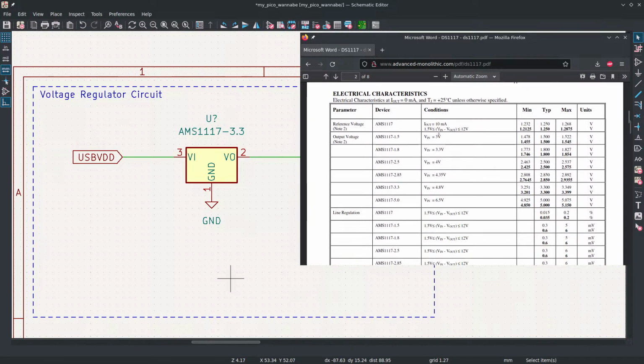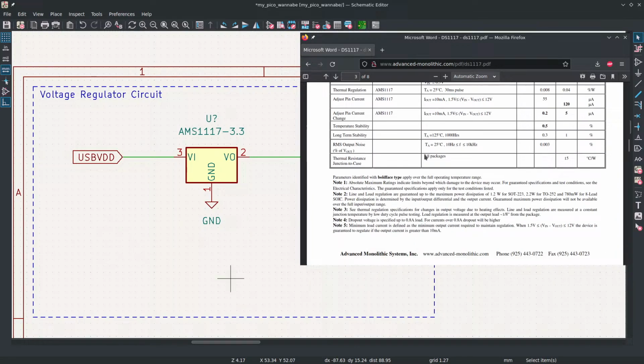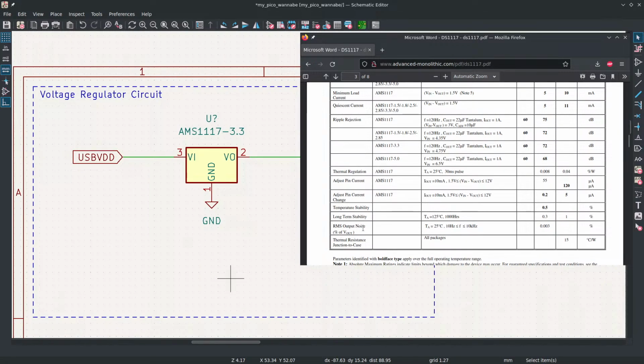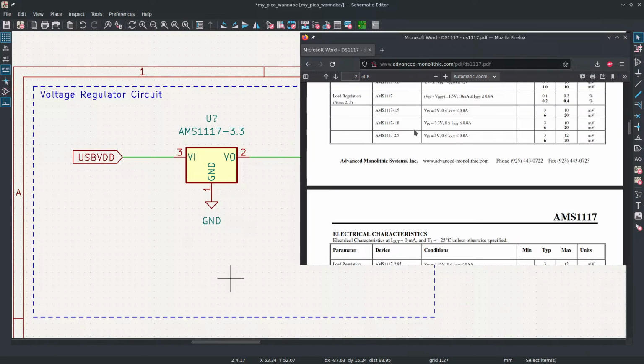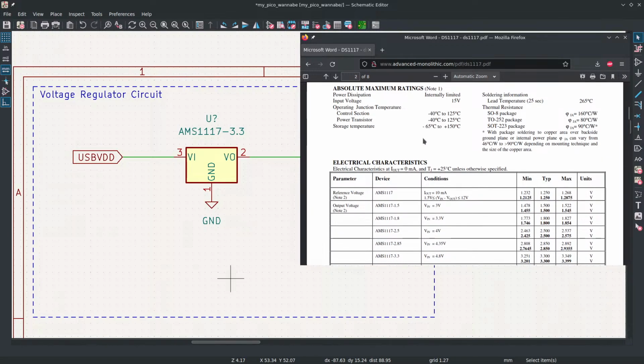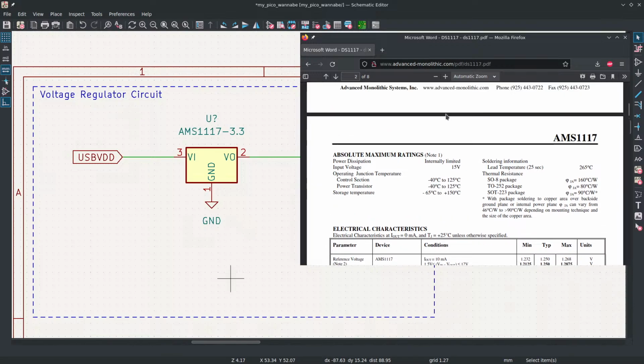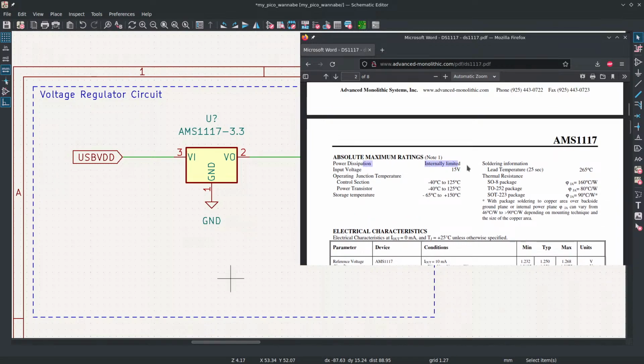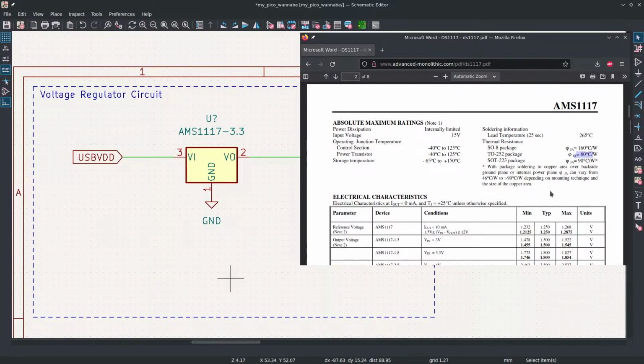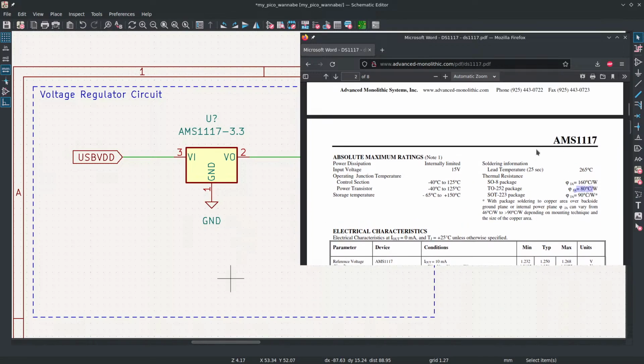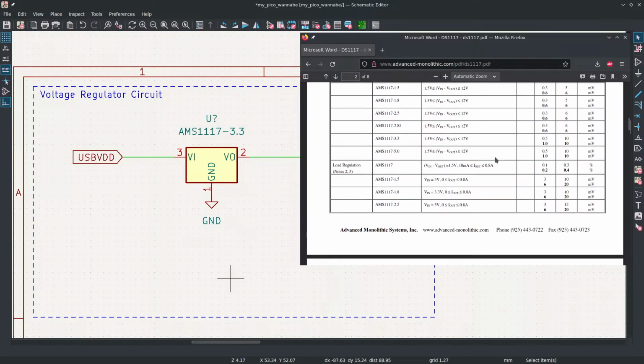Somewhere in the datasheet it'll say Safe Operating, or even Absolute Maximum. It'll tell you how much power you can dissipate. It looks like this one will actually turn off if it's too much. They tell you how hot it's going to get based on how much power you're trying to dissipate. But anything over about half a watt in these, I know from experience you're going to have trouble with. And half a watt comes up way faster than 1 amp does.